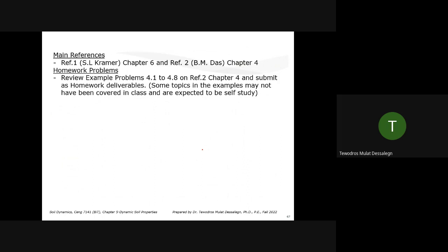That would be the conclusion of chapter 5. It's very practical and very interesting in soil dynamics because it touches numerical simulations, field tests, and lab tests. The purpose of this chapter is getting the dynamic properties of soil: the shear wave velocity, P wave velocities, and finally the degradation curves, Gmax and damping curves. We will see where we use the Gmax and damping curves, especially in chapter 9. It will be very interesting to see how you use it.